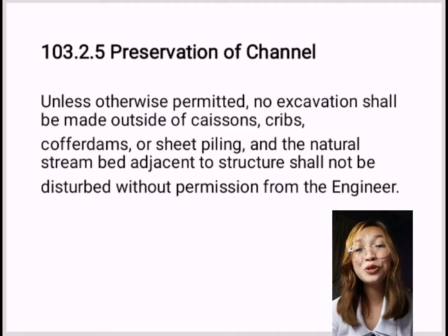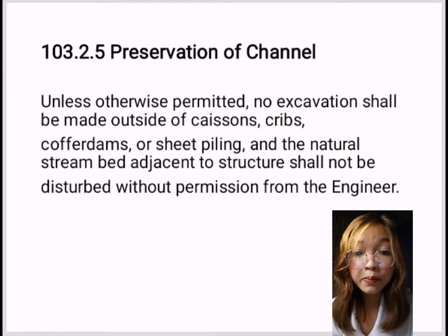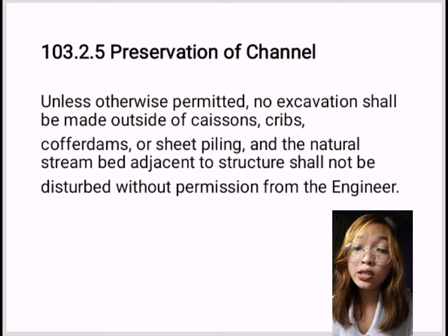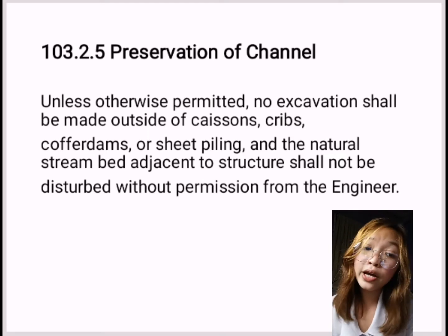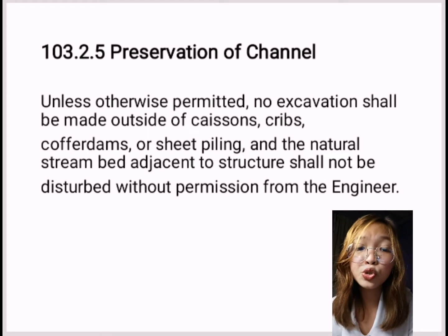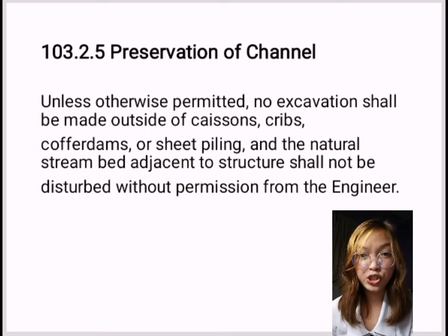So next, let's proceed to item 103.2.5, which is the preservation of channels. So unless otherwise permitted, no excavation shall be made outside of caissons, cribs, cofferdams, or sheet piling, and the natural stream bed adjacent to the structure shall not be disturbed without permission from the engineer.